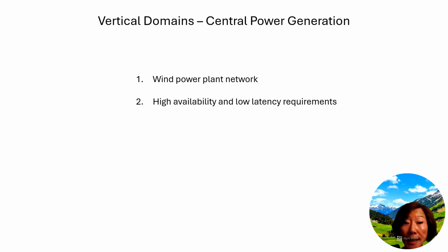To meet these extremely high availability requirements, 5G employs multiple reliability enhancing techniques. This includes multi-connectivity solutions, where each turbine maintains connections to multiple base stations simultaneously. The system also uses advanced error correction coding and hybrid automatic repeat request (HARQ) mechanisms to minimize packet loss.